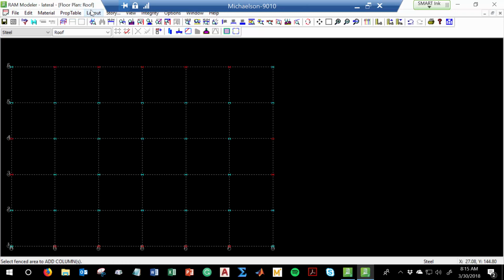That's really up to you. Now, let me say this. I'll give you a few minor hints. You need lateral frames along all four directions of the building. The point when you don't include a lateral resisting element along one direction, wind hits that direction, boom, building falls down. So you need lateral resisting systems everywhere.